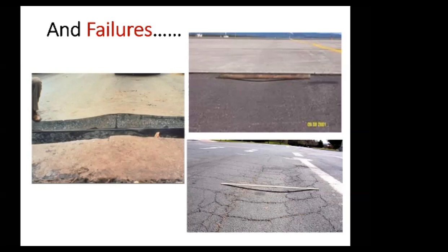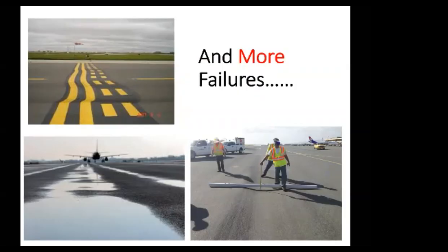And if you take a core in all of these 3, the rutting is not in the subgrade or in the unbound layers. So the pavement design is good structure-wise, but something's wrong in the material of the asphalt layers, because the asphalt layers are what really rutted. And again, more failures. We see it in so many different places, particularly in hot countries.